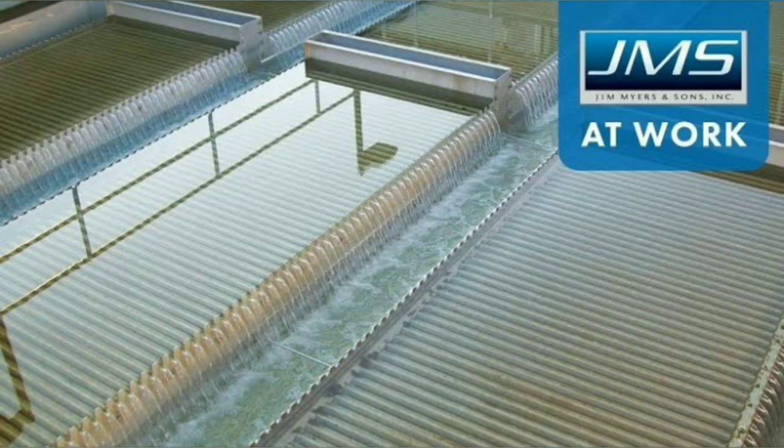The effluent, or the water after settling or removal of the particles, is collected from the plate sections, that is, passing through the orifice at the bottom now into the collection tubes, ensuring stable flow and maximizing the settling. And the flow passes out of the collection tubes and over the weir plates connected to the stainless steel collection troughs. And one advantage with this is generally these are made up of stainless steel.